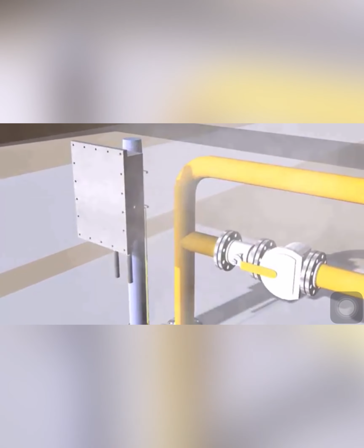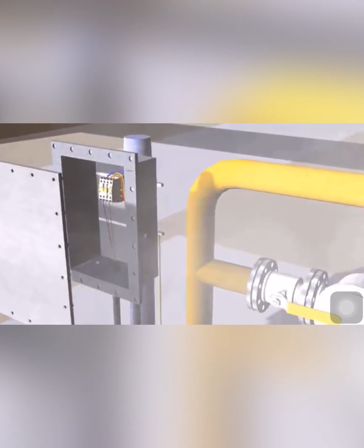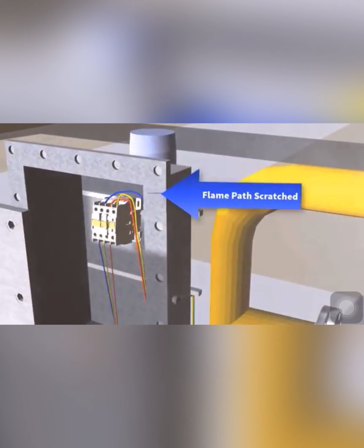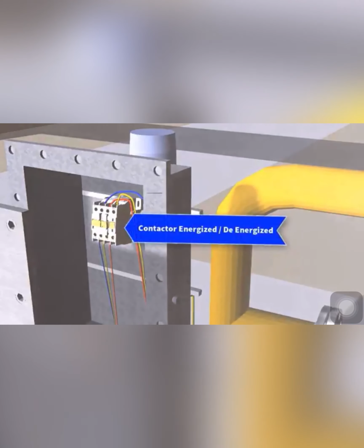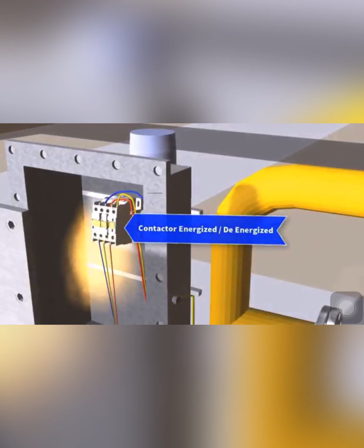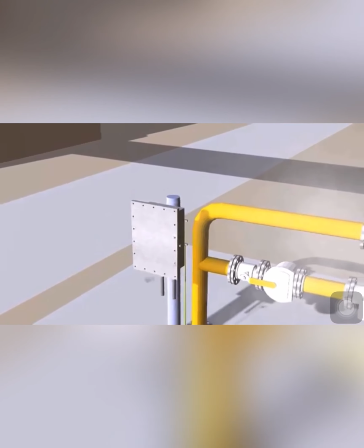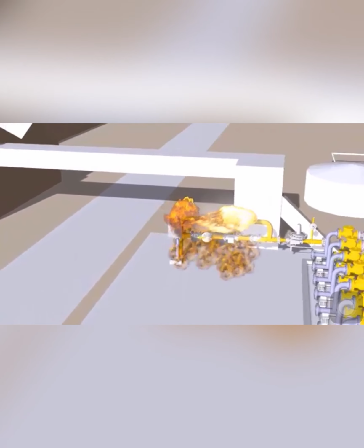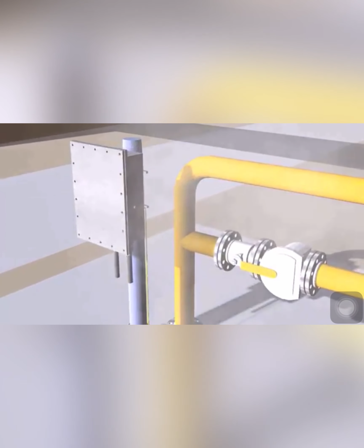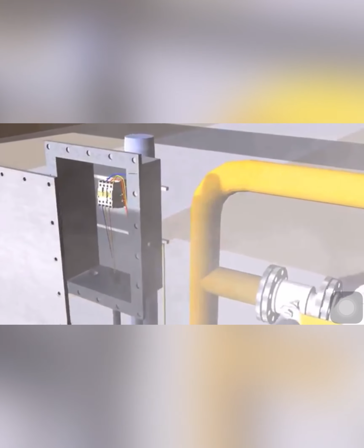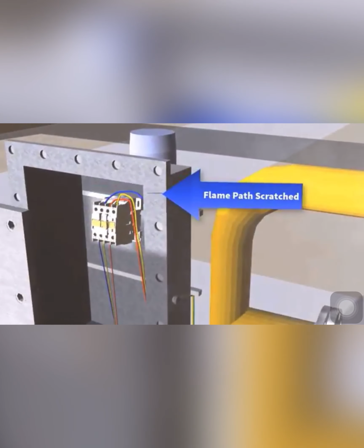Explosion-resistant design. Containers, apparatus, pipelines are built to be pressure shock resistant in order to withstand an explosion inside. The second one is explosion relief. Bursting discs or explosion flaps are deployed, which open in a safe direction if an explosion occurs and make sure the plant is not subjected to strain over and above its explosion resistance. And the last one is explosion suppression and preventing propagation of the explosion.